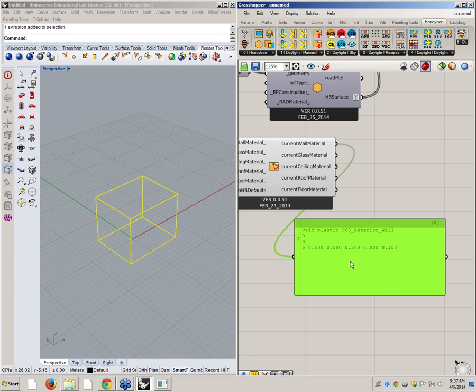This is how you can read it. And these two numbers are specularity and roughness. That's why I say it's just what you do in 3ds Max when you define a material, because this is how you define a material. This is a simple way of defining a material. This is not the only way you can do it in Radiance. But this is what people typically use for something like daylight simulation in buildings, right?